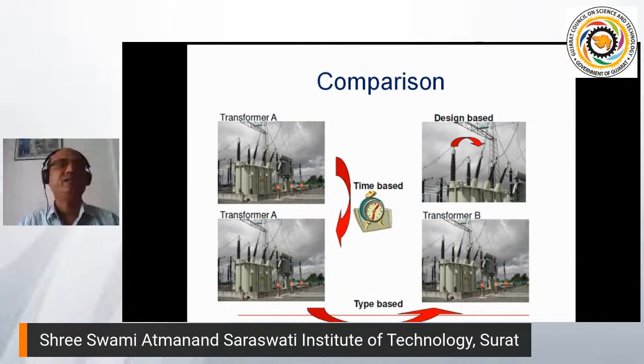What is done over here? This is also called signature analysis. Signature of two transformers, or the same transformer at different times, or the same transformer at two different phases, right? That is what time based means. So today you do an SFRA frequency response of a transformer A.